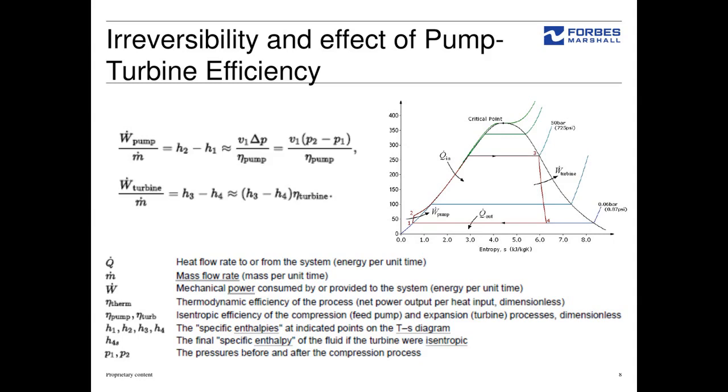So both process 1 to 2 and process 3 to 4 are irreversible processes, and that's why they will slightly deviate. Now when you plot an actual chart for your steam and water cycle in your power plant or in your boiler, you will find the chart is very similar to 1 to 2 or 3 to 4, slightly deviating from their vertical lines.